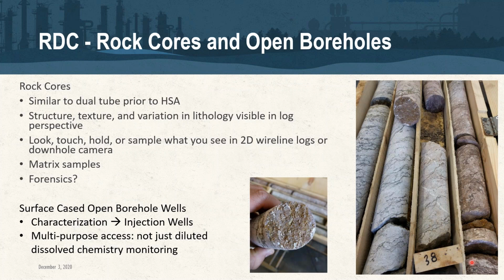So transitioning into what I want to talk about as importance for drilling considerations as well is getting into the character of the geology itself. As Derek had mentioned before, typically, consolidated geology monitoring investigation points are installed with air rotary methods or methods that essentially the end process is simply just to get a cased well in. But like he said, looking at rock chips coming from an air rotary hole, for instance, does give some indication of just general geology, but doesn't really tell us a whole lot of information about the actual nature and orientation of the geology itself.